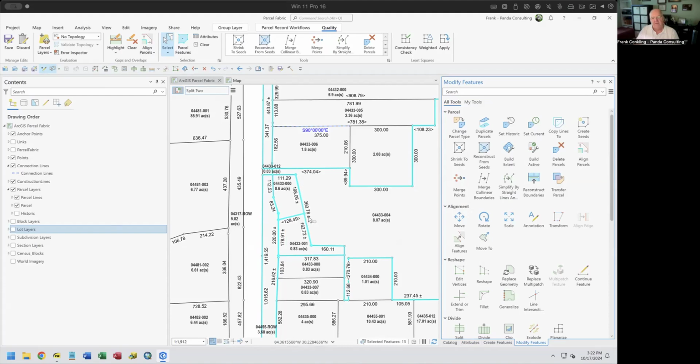And again, watch what happens with the labels, what it's actually telling me. And again, we have new symbology for the labels in that previously when it automatically went and just inversed where there was no dimension, it gave us these brackets around here. But because there was a dimension here at one time and we split that dimension, it's now giving us a plus or minus, meaning it's derived or it's been computed as far as the dimension.